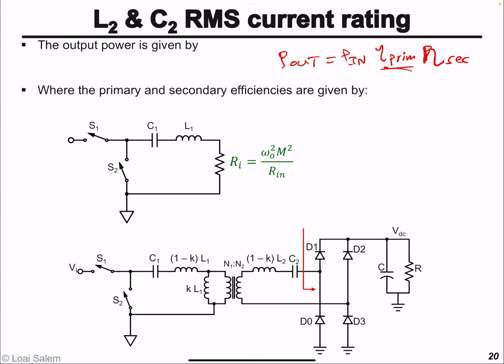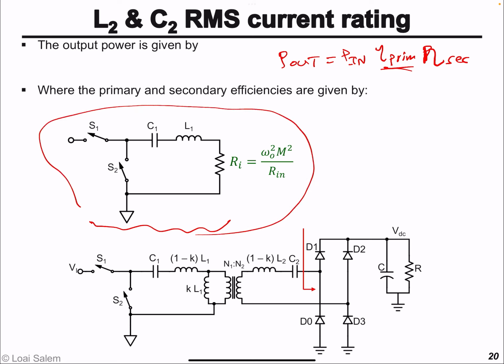Well, as we mentioned, essentially the transmitter can be modeled by this simple circuit. And so, as we know, there will be an equivalent on resistance R1 that's equal to the equivalent series resistance of the primary side, plus the equivalent series resistance of the capacitor RC2, plus the equivalent on resistance of the switches S1 or S2, as we did before, which is equal to RDS.